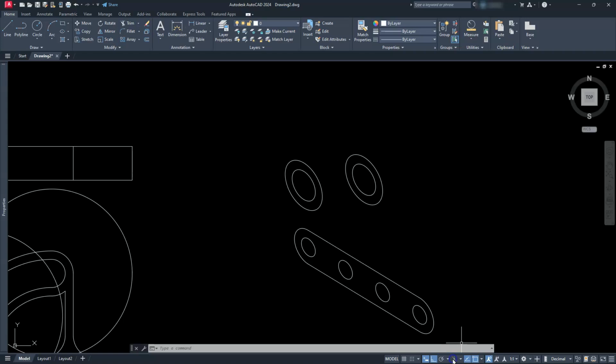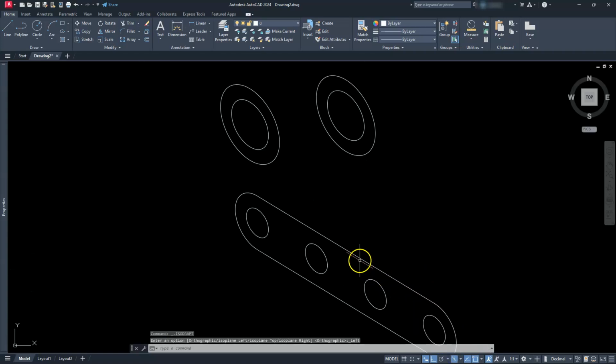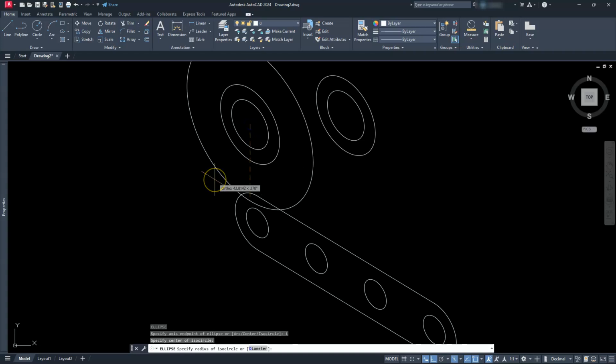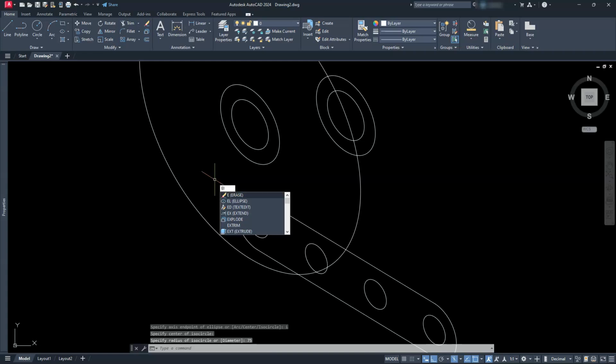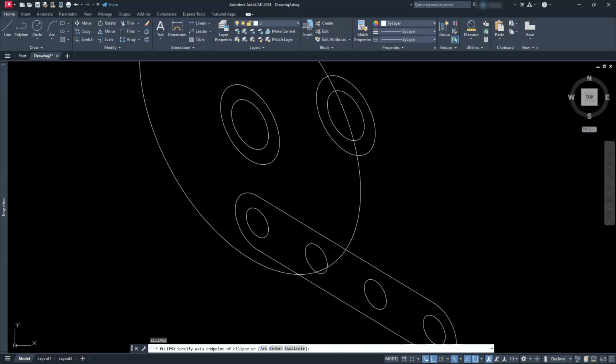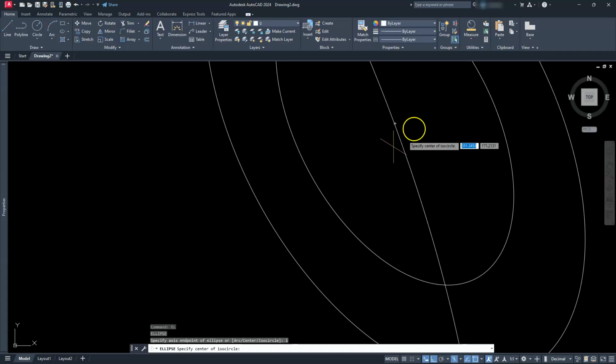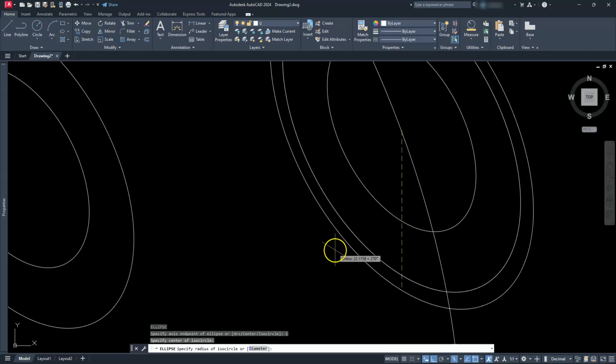So switch back over to your isometric drafting. I'll zoom into here, type in EL, enter, then I enter. Go find the center, click here, and then give it a radius of 75. Do the exact same thing again, right? So EL, enter, I enter. Go find the center here. And this is where you've got to be careful, because sometimes it might not be exactly on that center, so I want to make sure. And then this has a radius of 75.